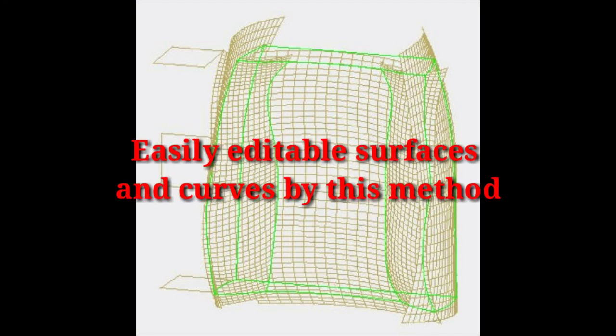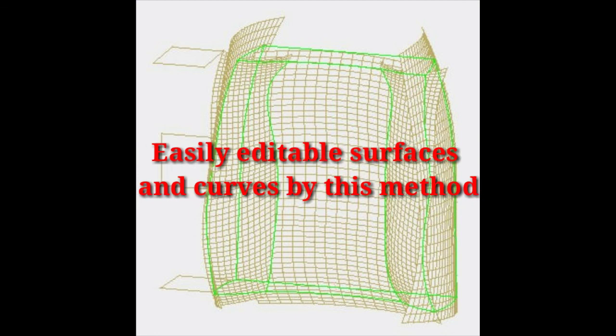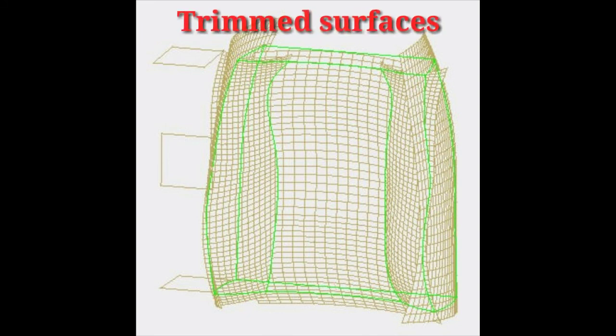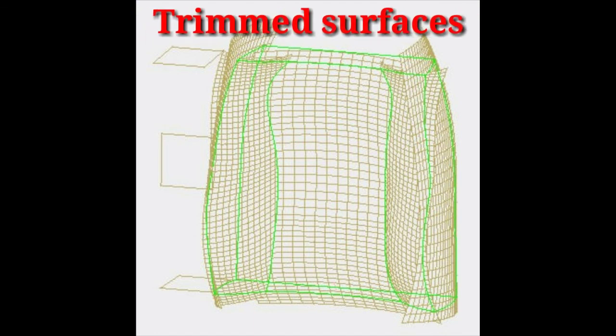Usually, these surfaces can be created by driving the curve cross section of the back, side or bottom along a line or an axis. After creating these surfaces or planes, they need to be trimmed back to each other to box out the volume. In the image you can see the surfaces trimmed back to each other; the back, top and bottom areas of the pad are planar, with the planes being shown. Surfaces trimmed to each other and planes.